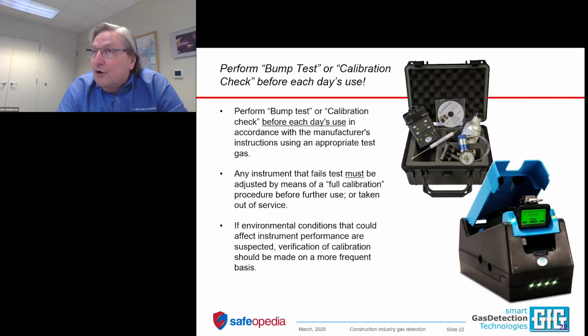And OSHA is very firm about the requirement in the construction confined space rule. You should perform a bump test, at least perform a bump test before each day's use, as well as any time that the instrument is dropped or harmed or exposed to conditions or materials that could affect the ability of the instrument to detect gas or affect the ability of the sensors to perform.